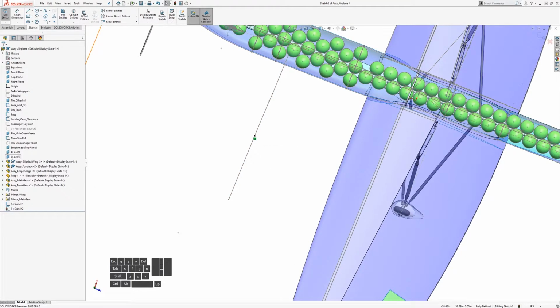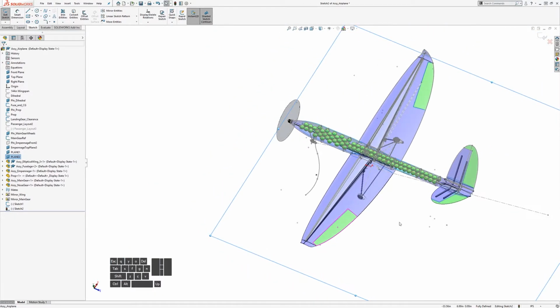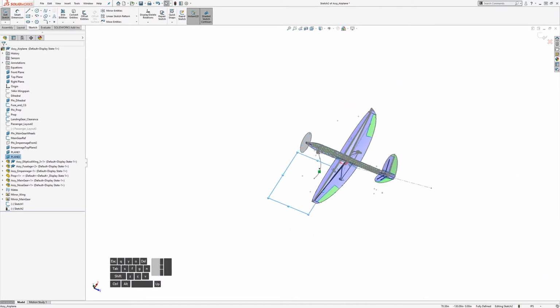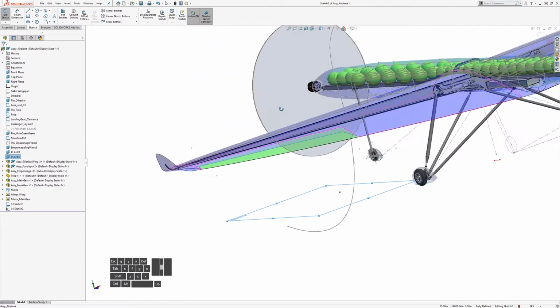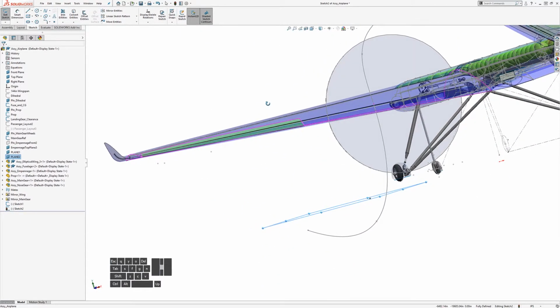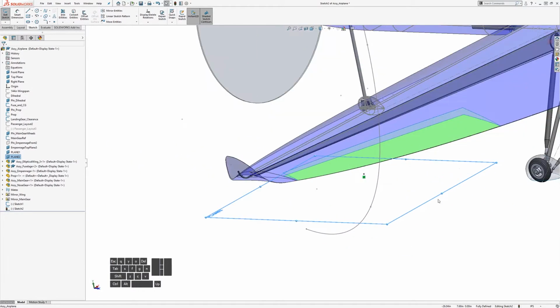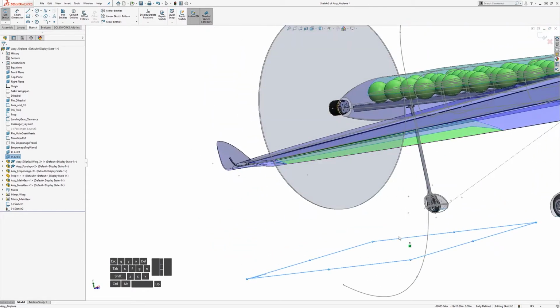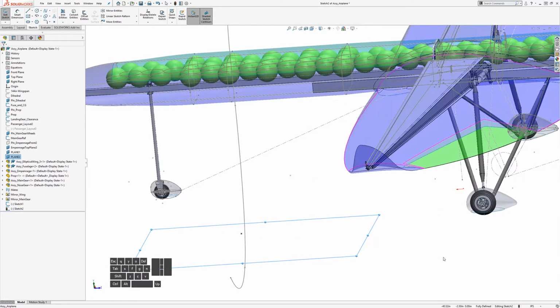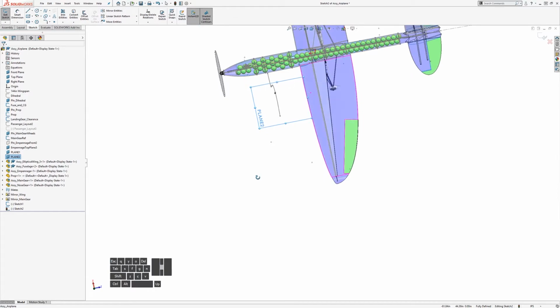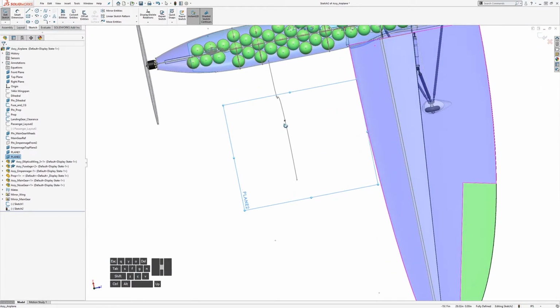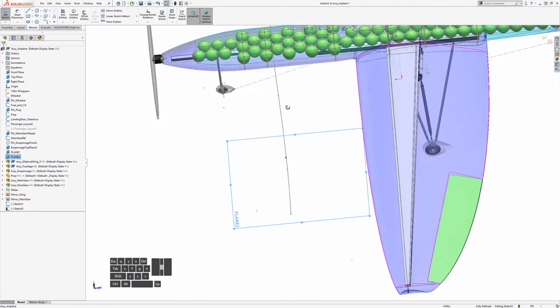So if we take the plane that we're drawing in, let's make it smaller just to be clearer. So that's the plane that contains our point, and it's trying to be coincident to that one. So what it did was sweep that plane down, and anywhere this intersects with what we're coincidenting it to, it creates a point there. So if we look from the top, it is coincident to that projection of that point.